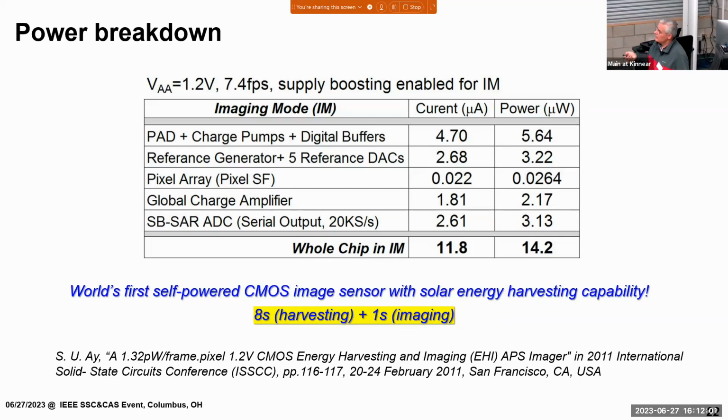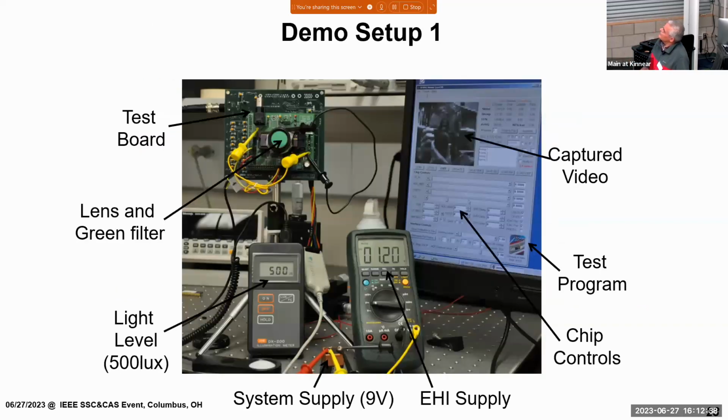Again, we would like to have a self-powered image sensor, but why do you need one? The main idea was, if we have a self-powered image sensor, we could implant it in the cochlea and maybe provide some sensing for blind people. You can read about that in our investigation of cochlear implant kind of systems. And this is the setup that we had, running everything on this battery, including the FPGA system, in room conditions, at a 1.2 volt regulated supply.